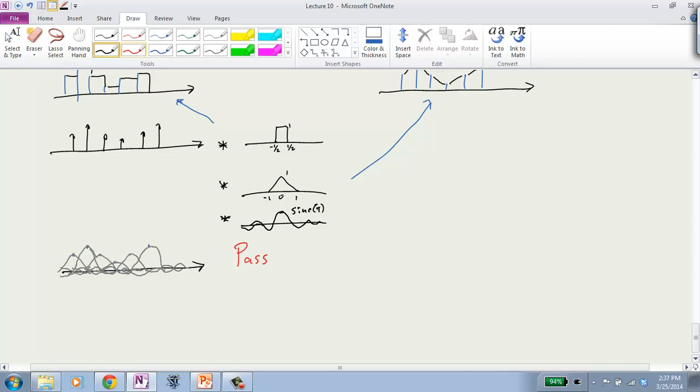That gives us our sinc interpolation. I've just drawn it out another way, what convolution with a sinc would be. Remember, convolving with a delta function is just moving your signal to that delta function and rescaling. So what I've drawn here is exactly convolution with a sinc.